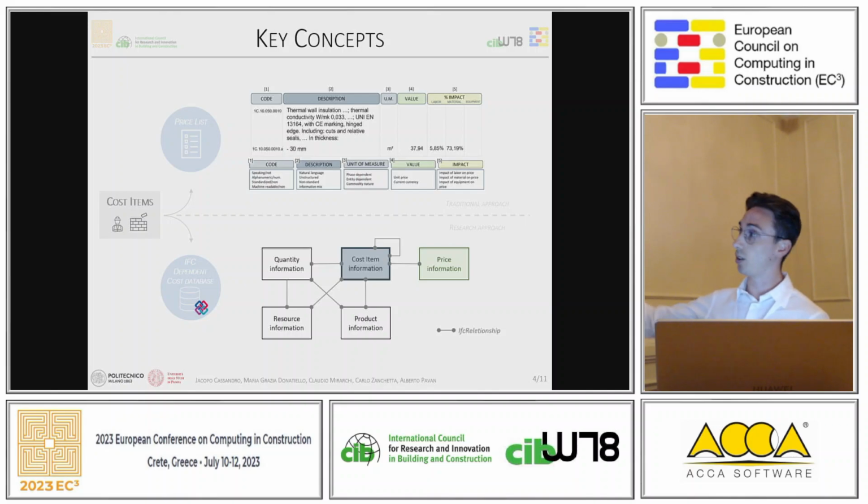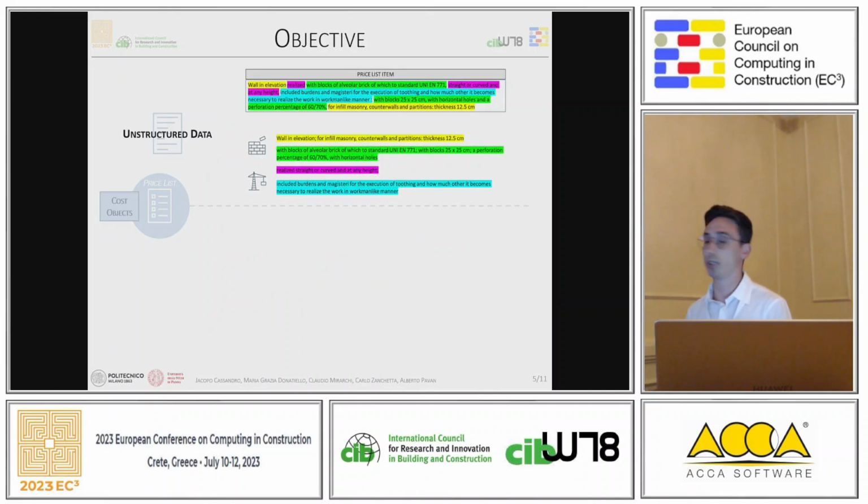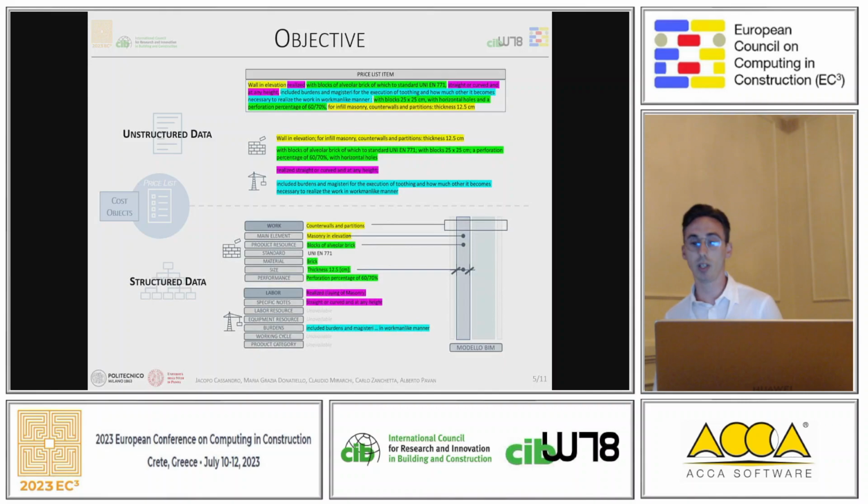As visible in the slide, the entity of IfcCostItem can relate with different information, such as price information, quantity information, but also with product and also resource, such as material resources, equipment resources, and labor resources. Currently, cost data is not structured, and this causes misunderstanding, inaccuracy, and errors in the selection and association of these price items to their respective geometric object. A structure with defined and standardized fields is necessary for the breakdown of the current cost items, and this will allow placing the information into specific fields or attributes by structuring data, ensure the validation and consistency between the attributes of certain cost classes and the attributes of the geometric object with which it is associated, and also consider the cost items no longer only as text strings but as replicable entities.